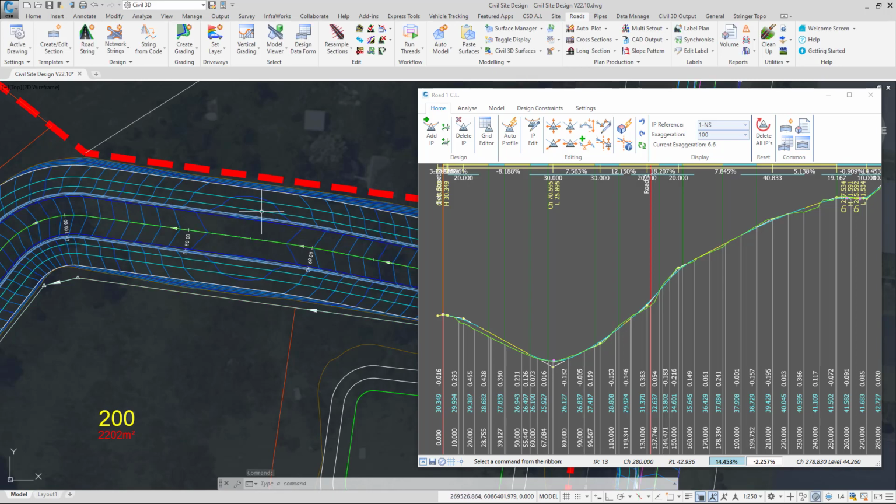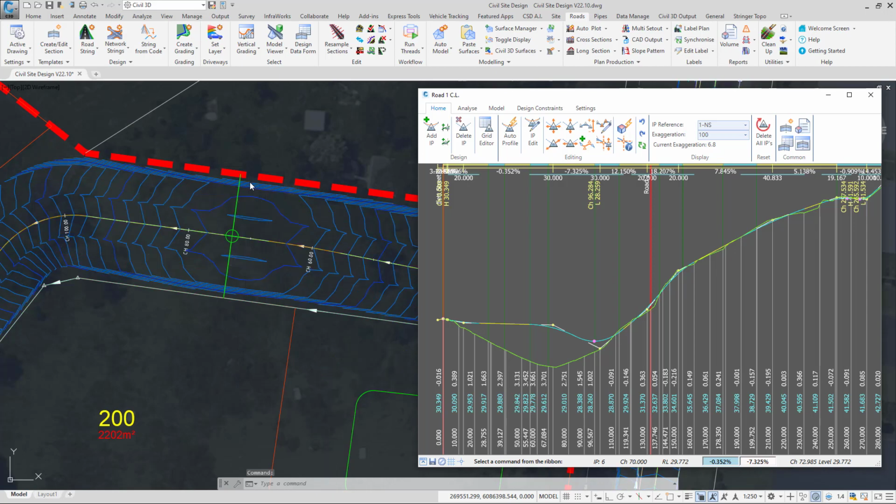In the drawing, we now have polylines being drawn for all of the line work associated with all of your models. This line work will also update. If I go ahead and make a change to the road elevations here, which in turn will adjust the batter line work in the drawing environment, when the model updates, the polylines will also update with those particular changes to the design.